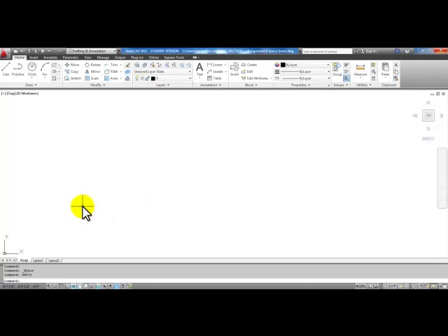If I draw a 17-foot line that went across the screen, it would extend beyond the view of this screen because this is only about 40 inches across. That's possible if you want to draw the line and then do a zoom extents to get up into a working space that's large enough for the posted floor plan, which is about 17 feet by 22 feet.